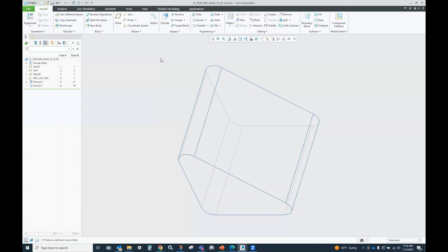That's how Creo works. And that's why, if you look on disk, Creo part files are so small: because it's really following a set of instructions on how to build the model. It's really not the physical 3D geometry or 3D model. It's building the model based on a list of instructions. So the better that you are at writing that list of instructions, the easier it is for Creo to regenerate the model. And in most cases, the model is more robust.